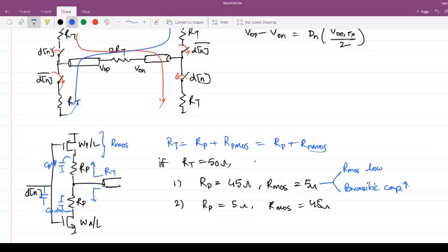So not only do I have a larger input parasitic cap, so that I have to use a larger pre-driver. It's not only that I use a larger pre-driver size, but also that the intermediate node capacitance creates a different problem. So you see that there is a benefit and a drawback in both of these designs. So what is going to dominate at a given data rate and what matching you require, you will choose a different point.